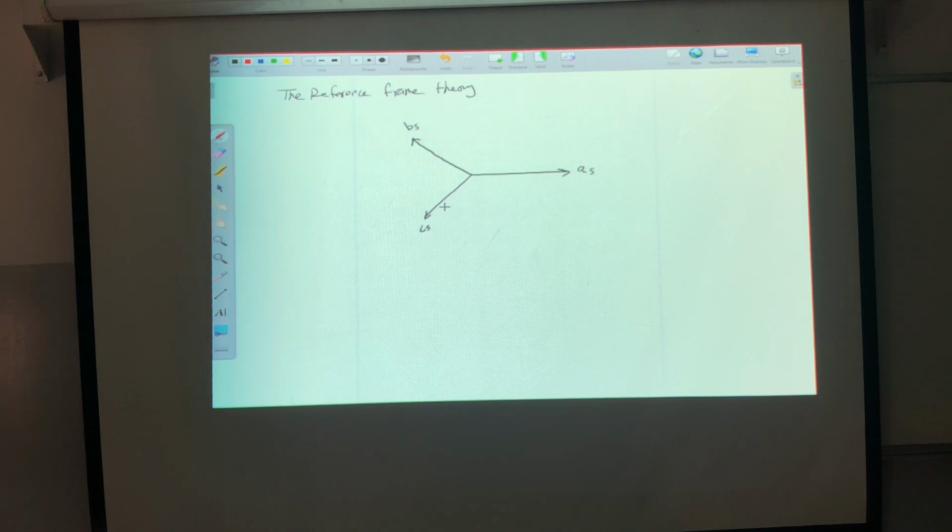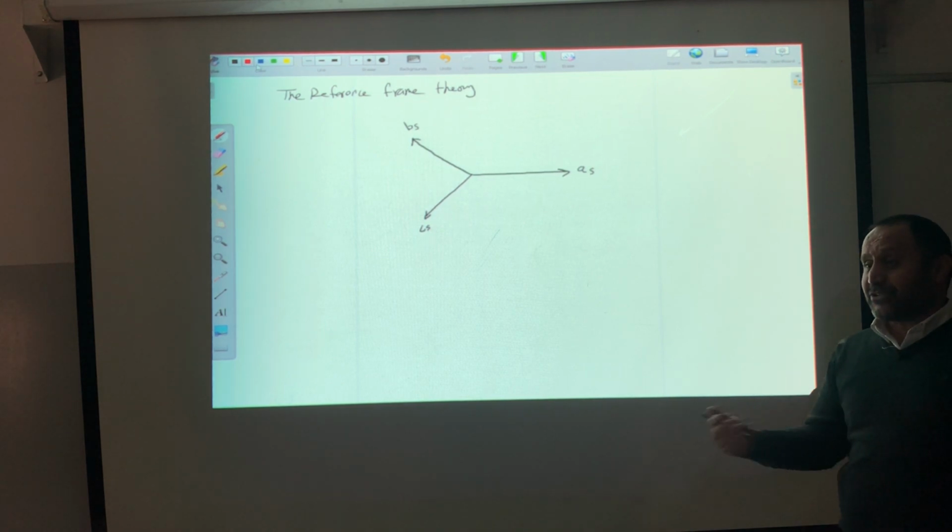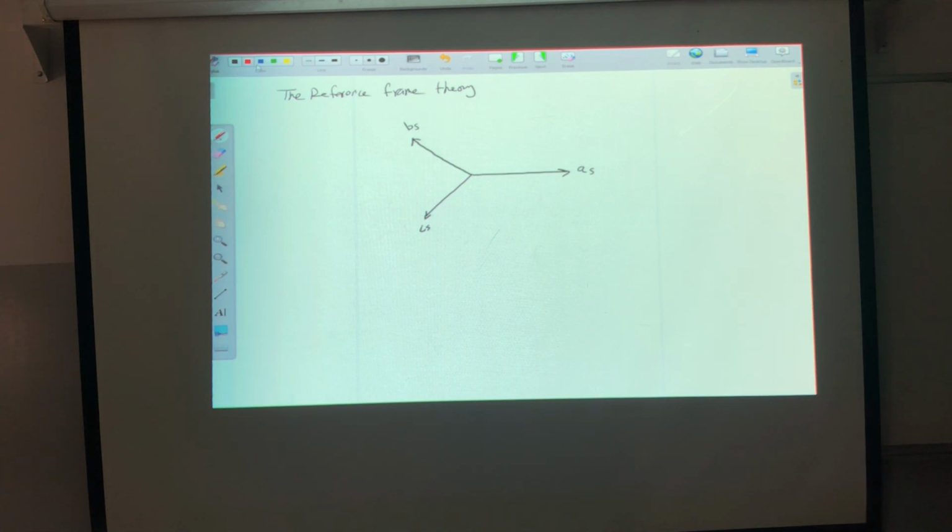Now let's assume that I'm having two axes, so I will transform three axes to two axes. Someone will say, why two, not one? To make it easy, instead of three, use one. But it's known that for the machine, in order to rotate, you need at least two coils. That's why the single-phase induction machine has no starting torque. Why? Because it has only one coil.